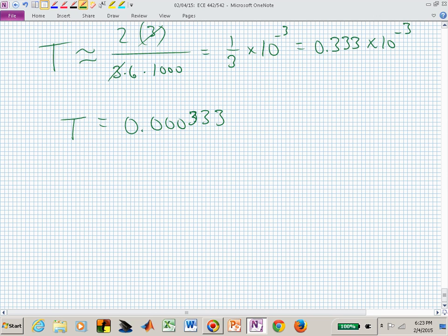Right now I'm just saying it's a rule of thumb, but it's a nice trade-off between sampling a lot faster than the Nyquist rate and not so fast that, you could say, just make that 1,000,000 times omega c, but then you're losing resolution. Now you're maybe jumping up 10 to the minus 7 in between samples, and that's not giving you any useful information. So it's this numerical precision and resolution that's a trade-off with this 30.